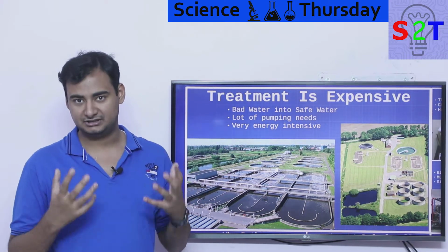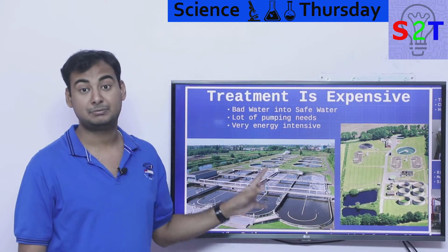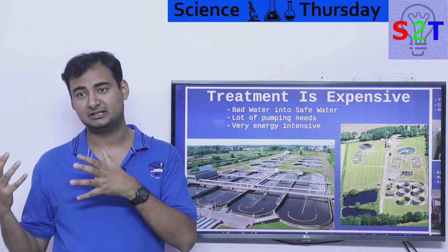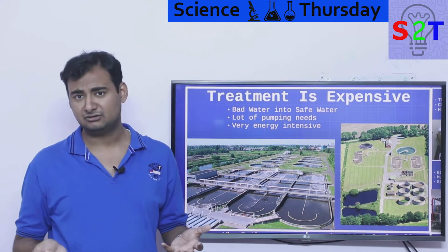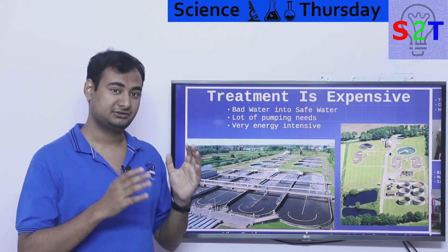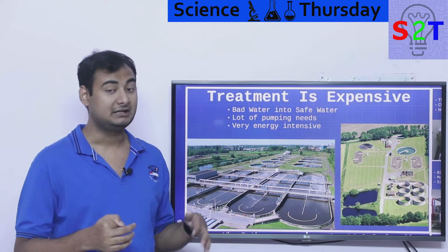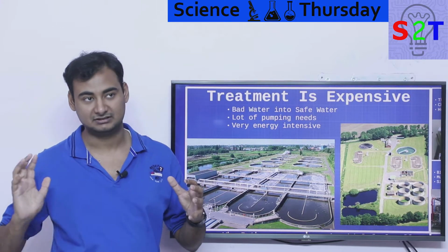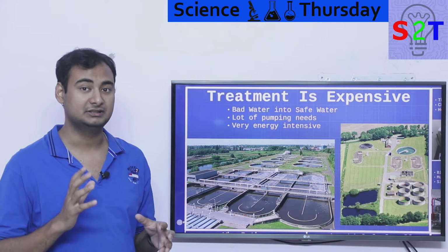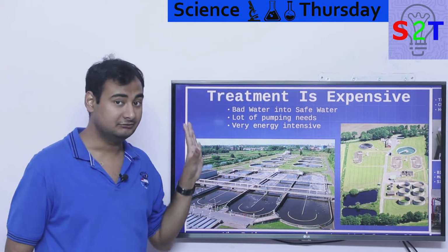And the primary energy draw in all these plants, whatever sewage treatment plant you have, is generally from pumping. Basically, you have air pumps and water pumps. And you have to understand, water pumps that are in your home doing your local thing are not very big. They don't have to be, because the water there is clean. But when you're talking about sludge and slurry, it's like using a pump to pump ketchup, and that's when you're lucky. Sometimes it's like pushing something even thicker upwards, so it takes a lot of electromechanical power to actually do the pumping. So pumping is a very, very serious power draw.